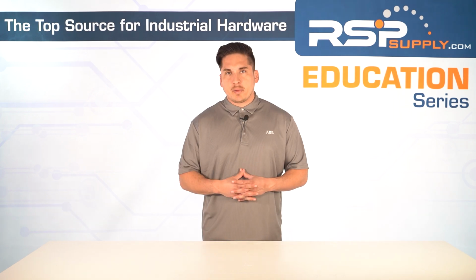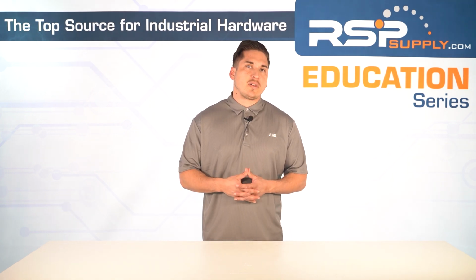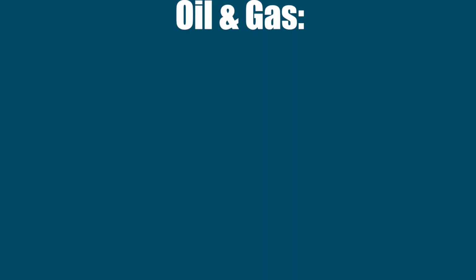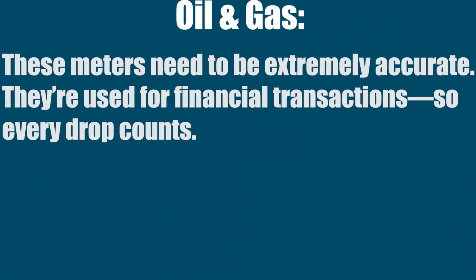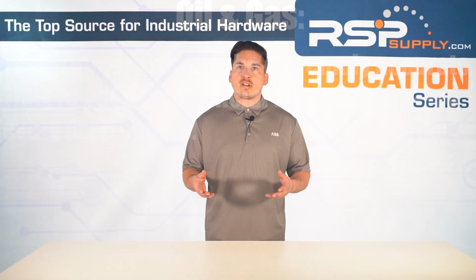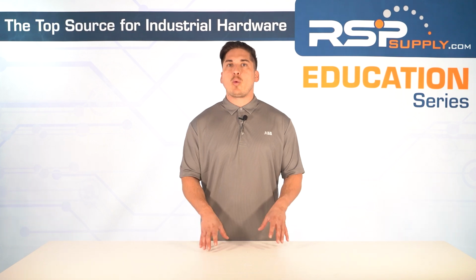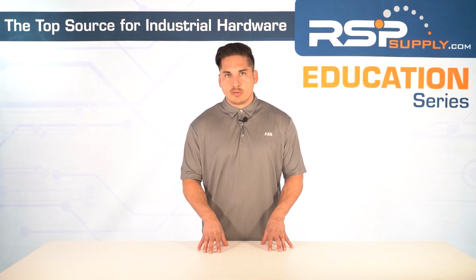So now let's get more specific about industry-specific instrumentation. Oil and gas, you're going to see a lot of custody transfer flow meters. These meters need to be extremely accurate because they're used for financial transactions. So every drop counts. Types include Coriolis, ultrasonic, and turbine meters. They often require API or ASTM certification.